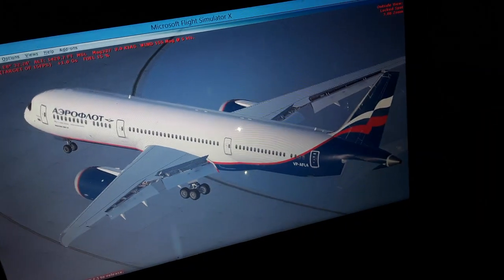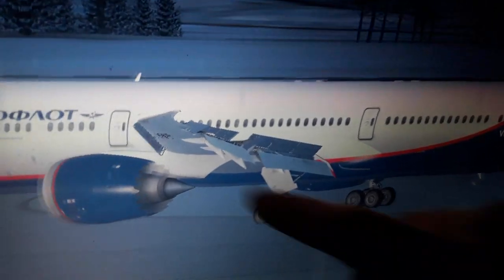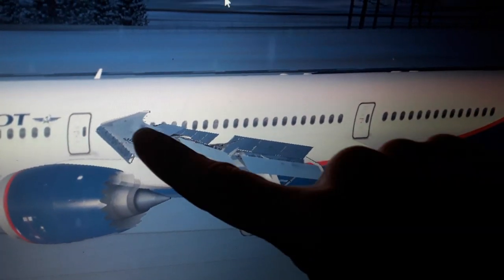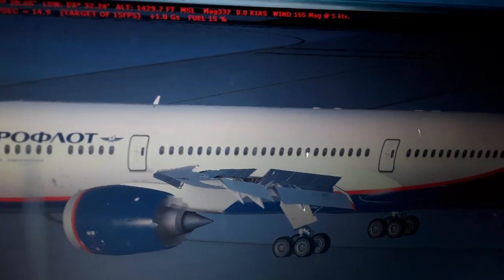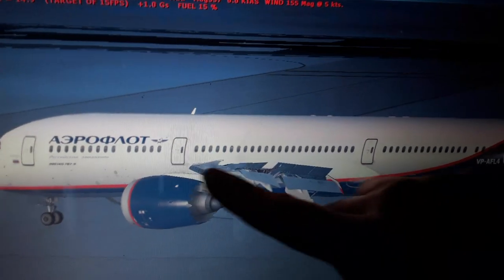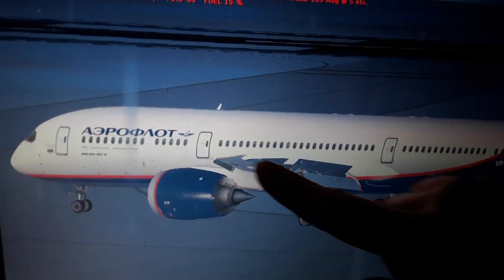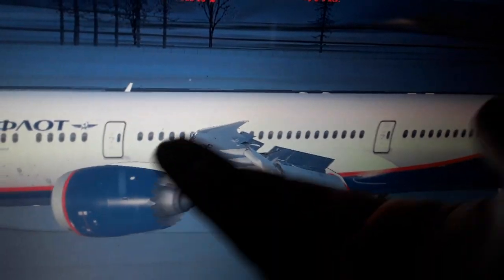Also you can see here one more from the aerodynamics. You can see the wings of the aircraft. The bottom surface of the wings is more flat, and also we have the flaps extended, and when we fly we have mainly a positive angle of attack of the wings. So using the Bernoulli theory of fluids, the airflow is moving slower below the wings, so we have higher air pressure, which pushes the aircraft weight and wings up into the air as we fly.